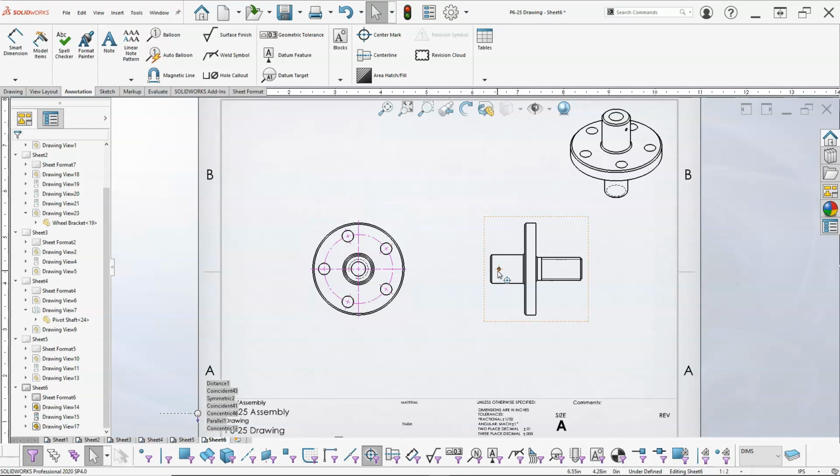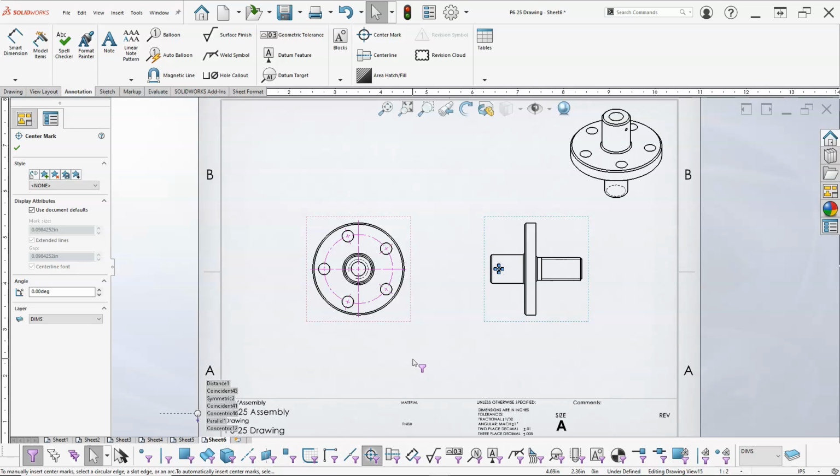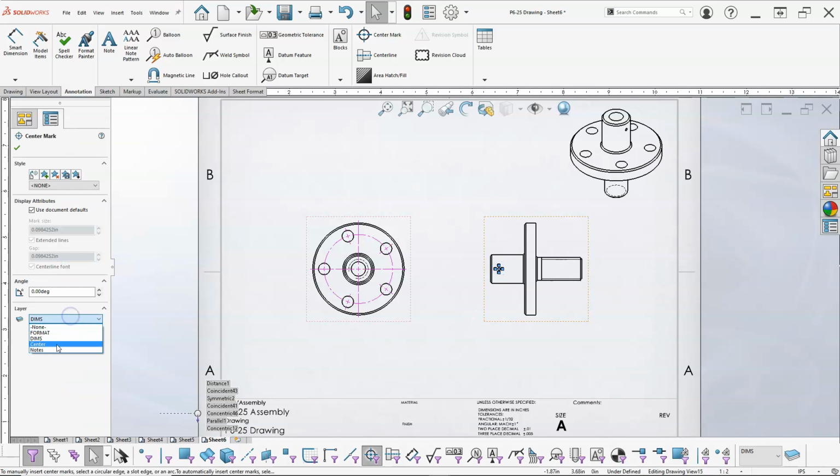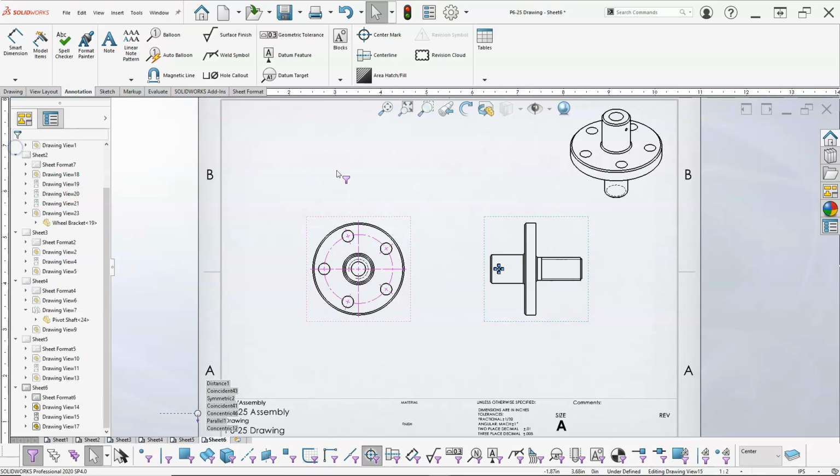And we'll grab that one, and then F6 will toggle it off. So since that one's active, I'd be curious. Oh, I guess I selected it. F6 toggles it on as a selection. I can apply it this time, and then F6 will turn it back off, leaving center marks as the filter of choice.